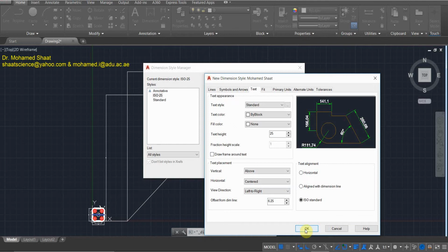If you feel for some reason that this reference number is giving us inconsistent dimensions to the drawing or to the shape, you can increase it up or you can increase it down. But keep in mind that you should have a reference number, right? So based on my use of this software, 5% of the average dimension of the drawing is very acceptable to give a consistent size of the dimensioning, and this is what we're gonna use.